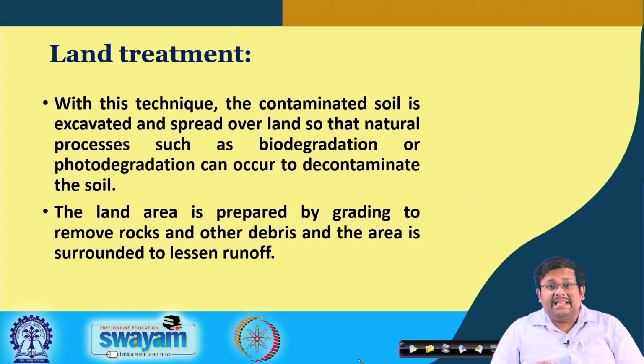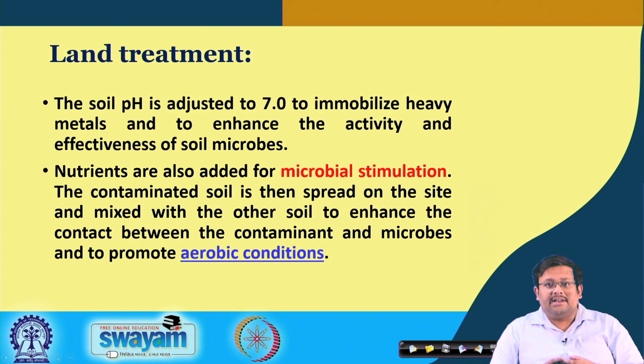Remember, the land area which is used for land treatment is prepared by grading to remove rocks and other debris, and the area is surrounded by a berm to lessen the runoff, because if there is runoff, then there will be a chance of movement of contaminants from this contaminated soil to other areas where contamination is not present. So, this is about the land treatment. Let us move ahead and see what the other aspects of land treatment are.